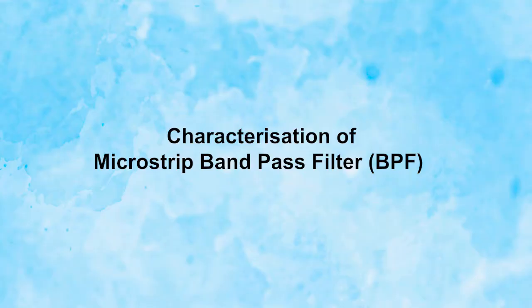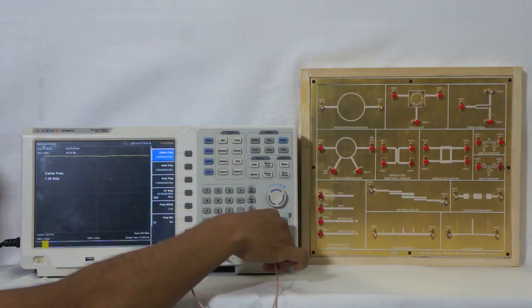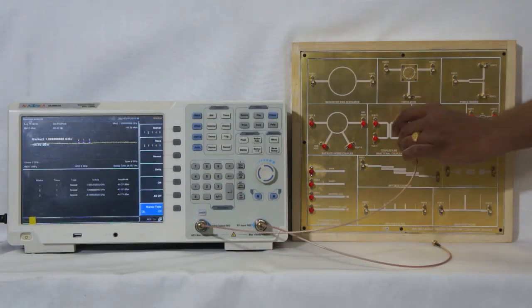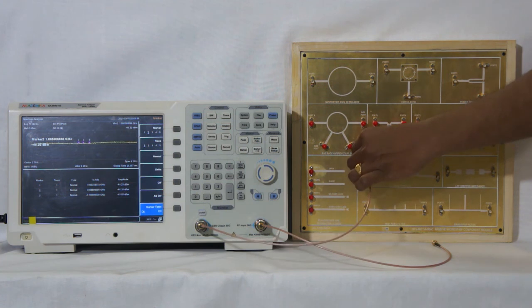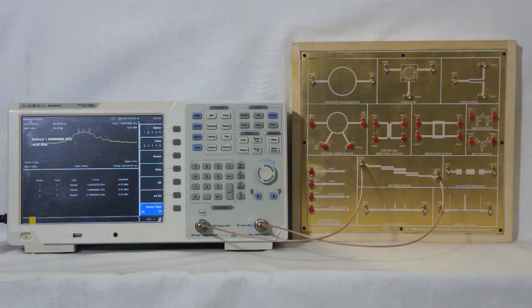Characterization of microstrip bandpass filter. Set the tracking generator of the spectrum analyzer to 0 dBm and connect to port 1 of the bandpass filter. Connect port 2 of the bandpass filter to the spectrum analyzer. Set the frequency range on the spectrum analyzer accordingly.